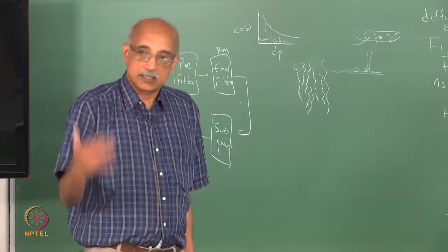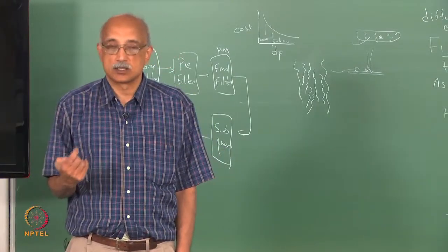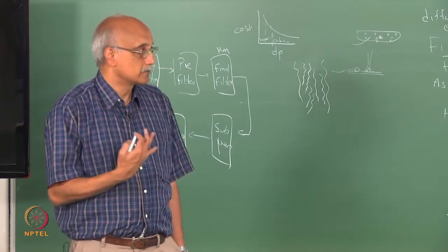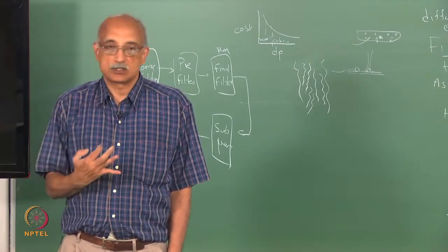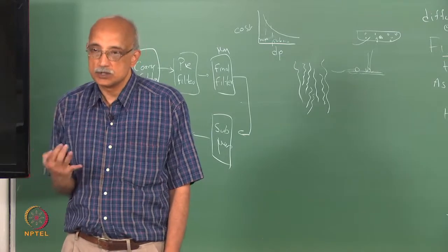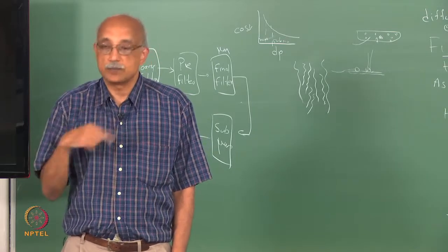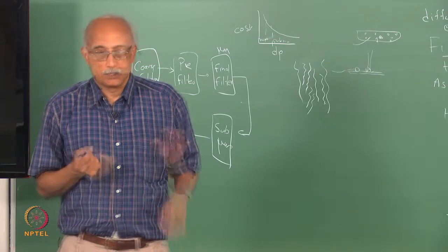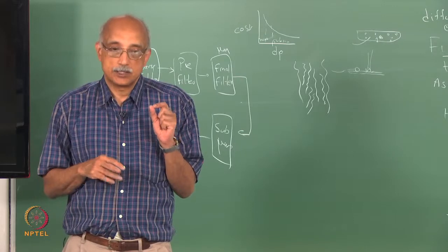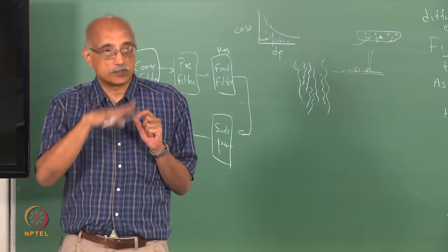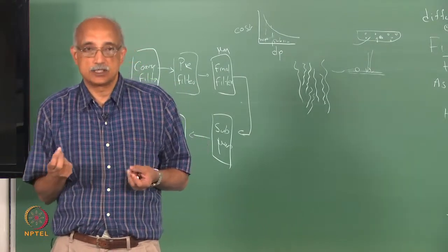Of course, you can do this by size, you can look at filter efficiency for various size ranges and so on, but essentially it is a simple characteristic. You know how much material you are passing over the filter, and you know how much is getting retained. So, that gives you the capture efficiency, but it is not so simple when you talk about a filter bed, because in that case the efficiency of capture of a single filter or a single fiber is one thing, but the overall capture efficiency of the filter is going to be a summation of the filtration efficiencies of single fibers, right.